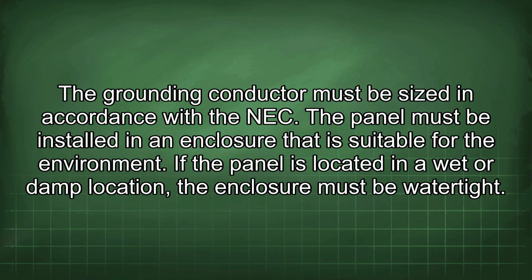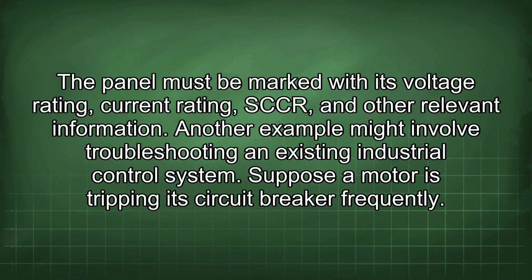The panel must be installed in an enclosure that is suitable for the environment. If the panel is located in a wet or damp location, the enclosure must be watertight. The panel must be marked with its voltage rating, current rating, SCCR, and other relevant information.